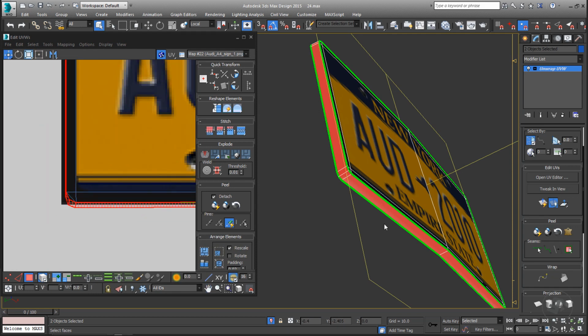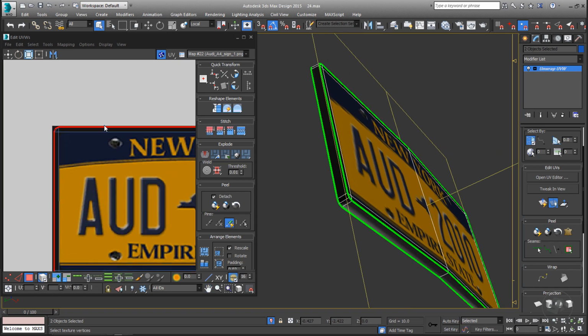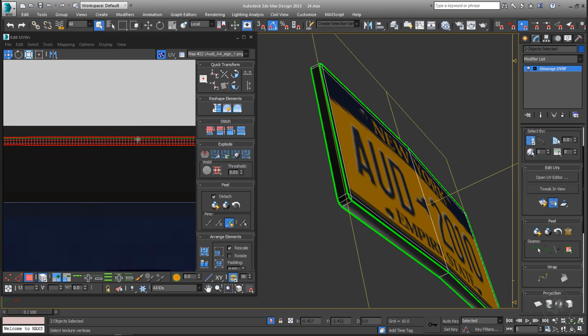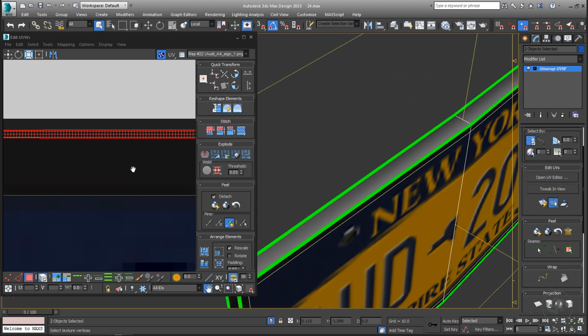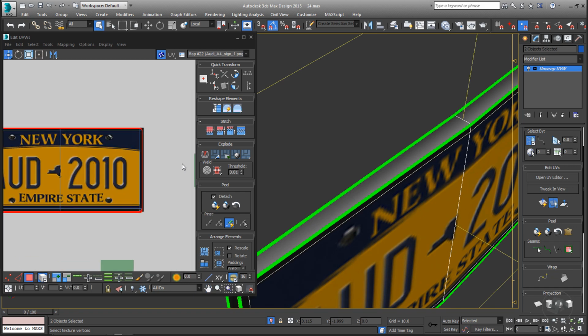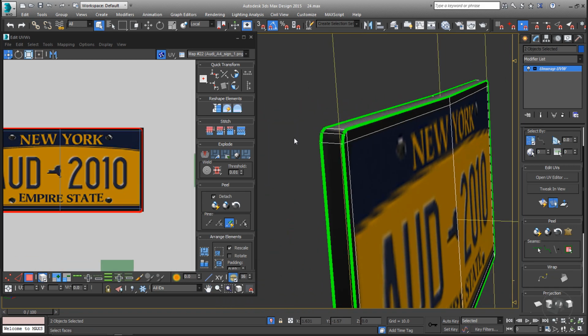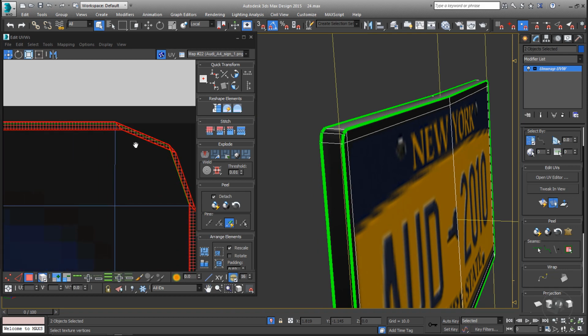This unwrapped chunk of UVs is exposing and extending some UVs that we do not actually intend to use. We need to adjust this UV map so that, when sending the UVW template to the 2D artist, there will be no confusion or misreading of the template.